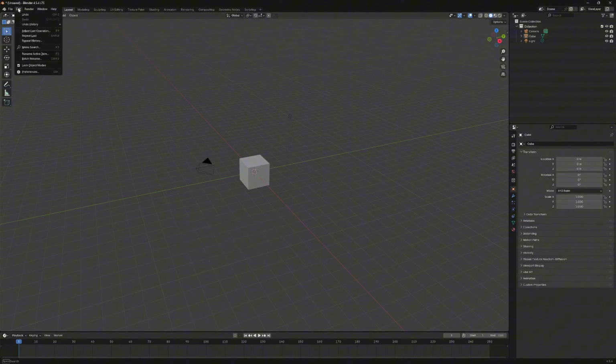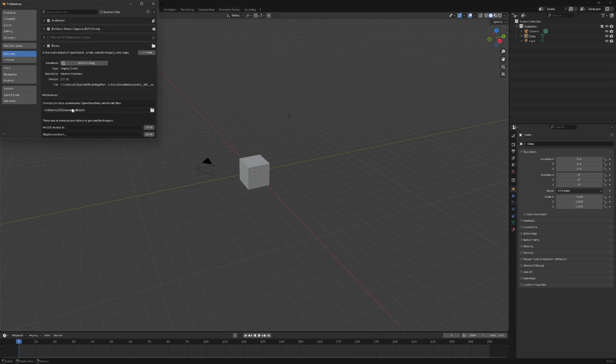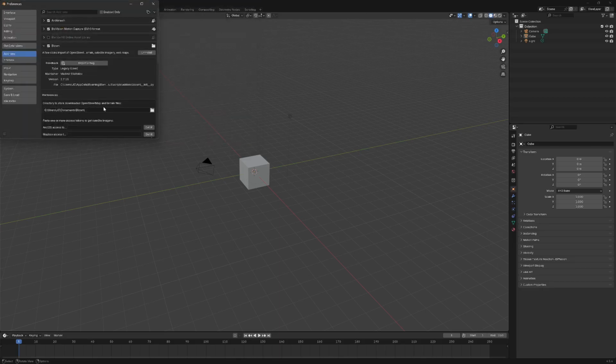And what you'll then see up here, when we go back to preferences, is something called Blossom will appear here. Okay, so once we have that appear, what we then need to do is specify a file by opening up the arrow where we want these to be saved. So I've just created a file called Blossom in my documents. I'm just going to save them in here, and I'm going to click OK and accept. And I want you to do the same thing. It's really important that we do that step.